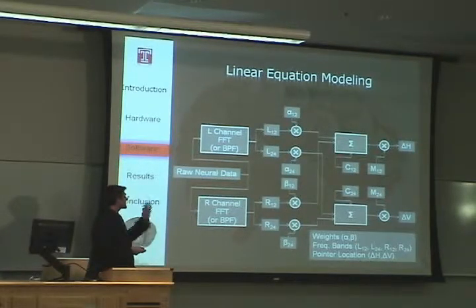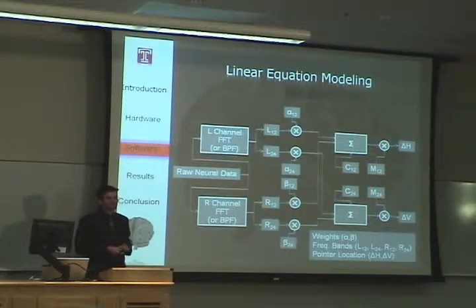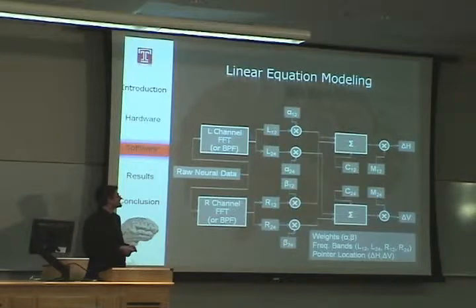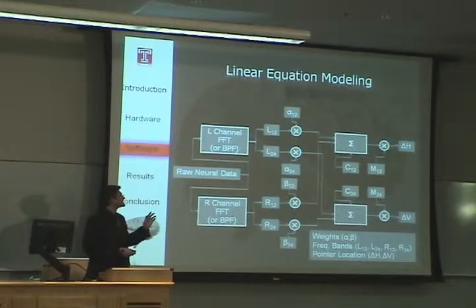And what's kind of happening here? You guys have looked at all the neural data that comes in time domain, from the brain. And we break it out into each separate channel. And in particular, we're only using 2 channels. And we do fast Fourier transforms. We pull out frequency data, pull out 12 and 24 hertz for each of the 2 channels.